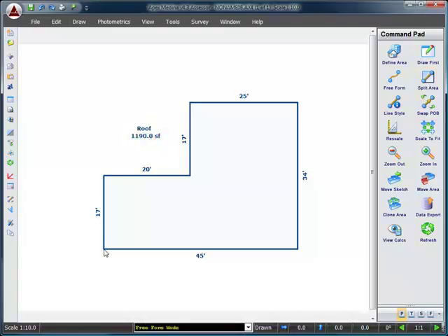And now I'm going to jump into freeform mode so that we can draw the roof's ridge lines. 8.5 feet up, put my pen down, let's draw straight across to the right side of the property. Come back 12.5 feet, then draw a line straight up. Got a couple more lines to draw. And that's our roof's ridge lines. Next, I'm going to jump to this point and draw what will represent our equipment wall.